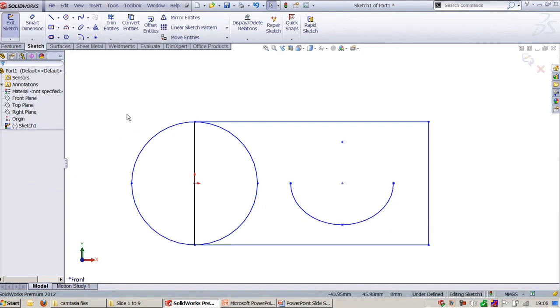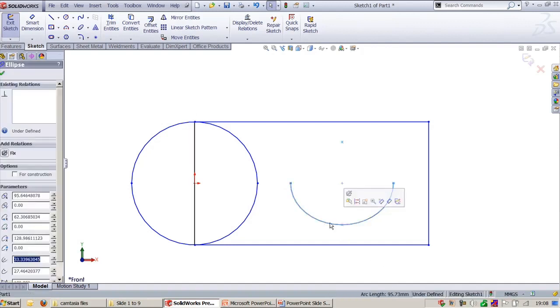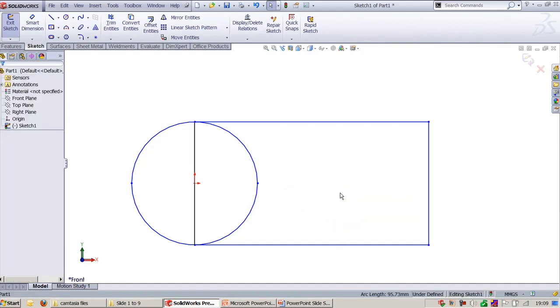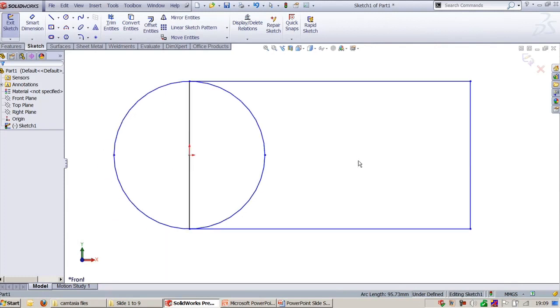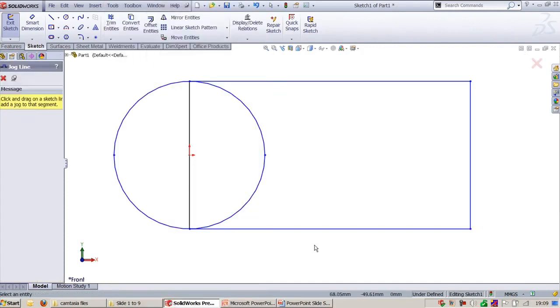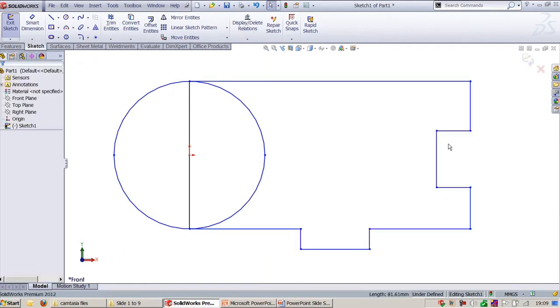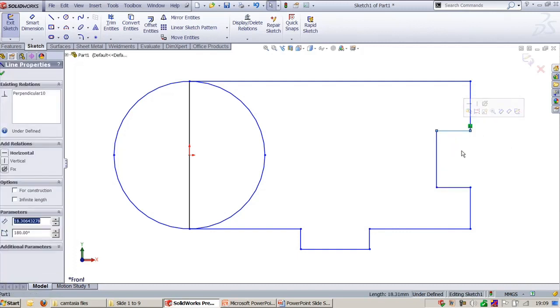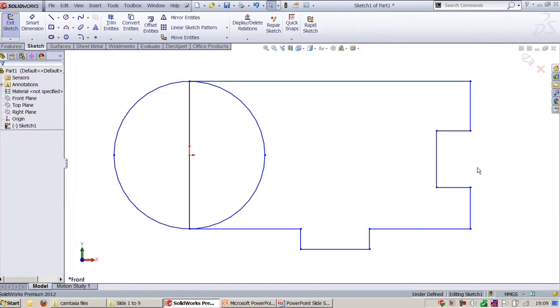Next let us look into jog. Jog is especially used in sheet metal work where you want to create intermittents. I will go to Sketch Tools. Here I have jog line. You select the horizontal line. You can add horizontal and vertical segments here, and these line segments will be created with the perpendicular, horizontal and parallel relationships. So you don't need to worry about applying the geometric conditions once again for these entities.